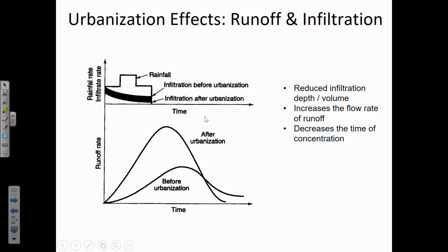You know, broken twigs and leaves and an irregular ground surface, the water moves kind of slowly over that kind of a surface compared to a smooth graded asphalt, concrete, or even just a bare earth that's been graded. And so the water arrives sooner. And those two things are interrelated. The fact that it's arriving sooner is part of the reason why the peak is higher.